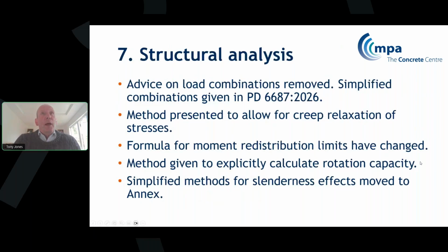Moving into structural analysis, the advice in Eurocode 2 on load combinations has been removed, simply because, as we've heard, that is the remit of Eurocode 0, and it was never really the remit of Eurocode 2. However, given the nature of concrete and the fact that we have continuity and moment redistribution and cracking, etc., we have put simplified combinations in PD 6687 2026, which you'll be familiar with from previous guidance in national annexes and in the main code itself.